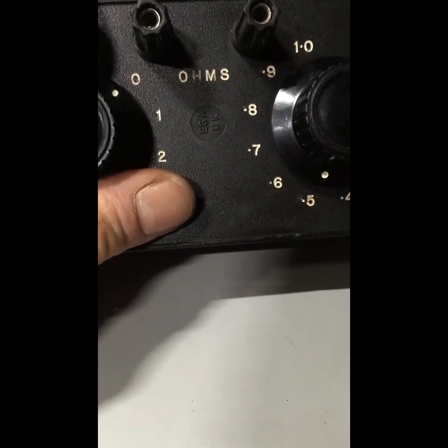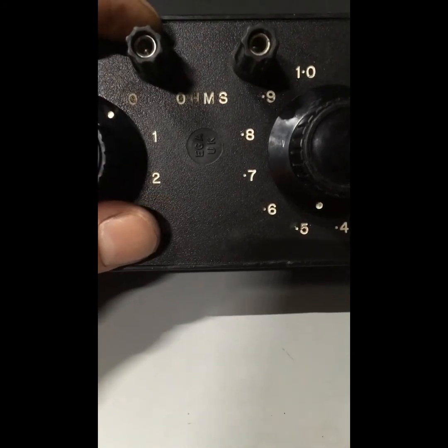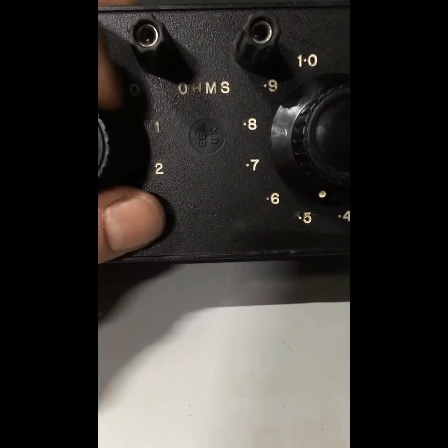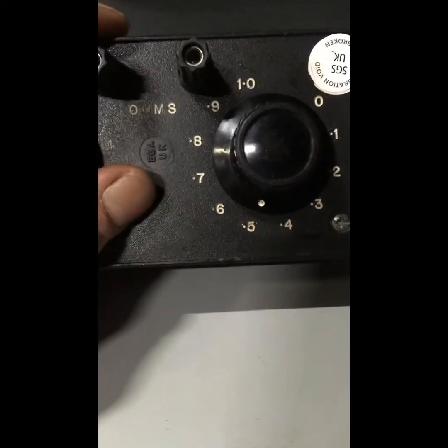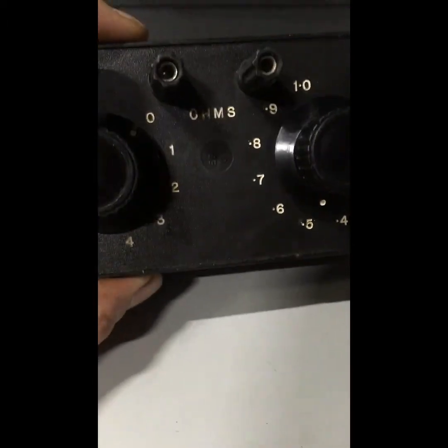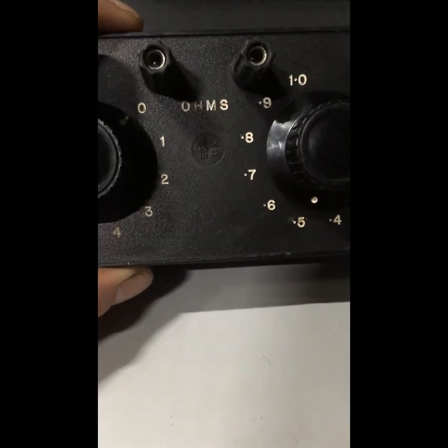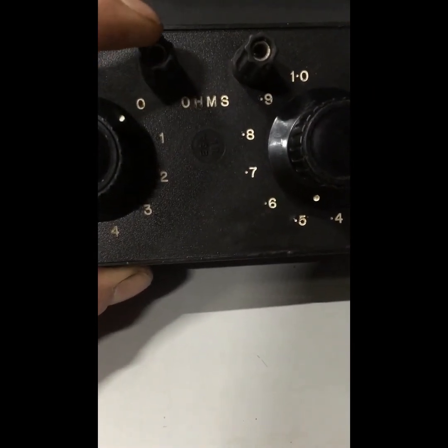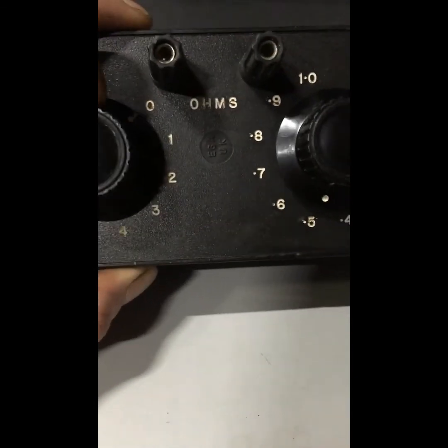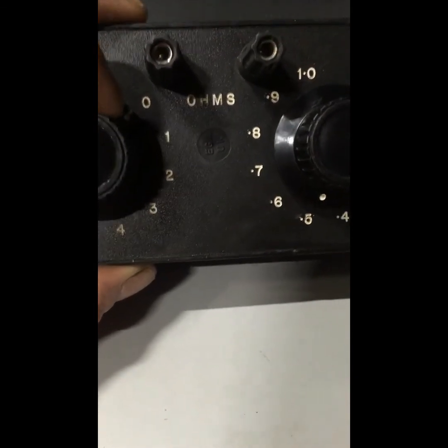The only difference you will ever see is on, say, an AC track circuit, where they can be very close together, so you could have a drop of say 0.7 and a pick of 0.9. But these things are in your standards for your own railway. But that's the standard DC shunt box. There are different versions of this, and that's what we use to set it up, put on at the relay end on the track leads.